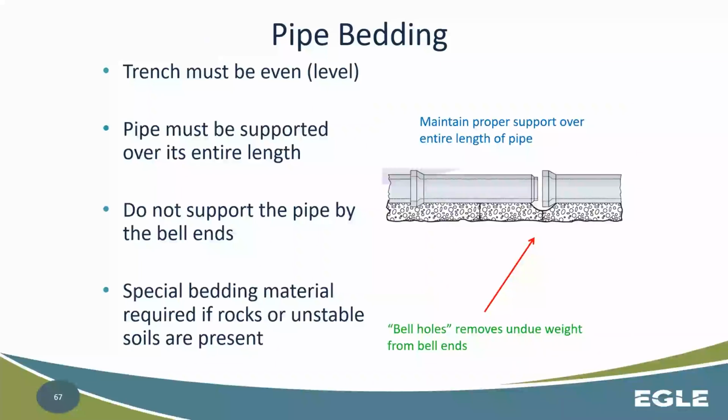So pipe bedding, we've talked about this quite a bit, but in general, you're just making sure that trench is level, make sure that bedding is adequate. Okay, making sure that it's that clean sand. Okay, it supports the whole length of the pipe, right?